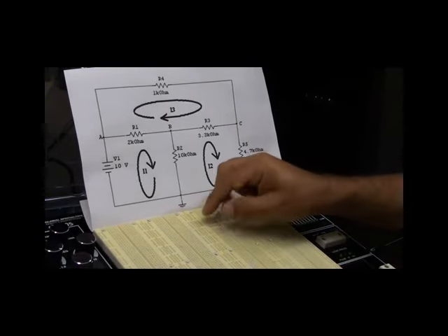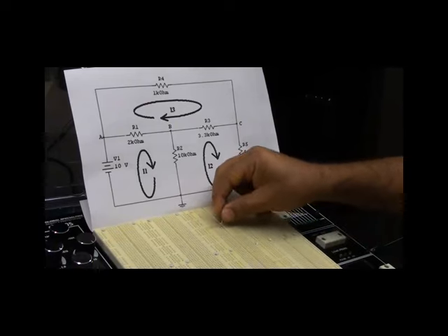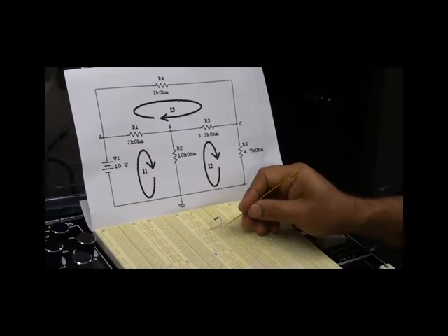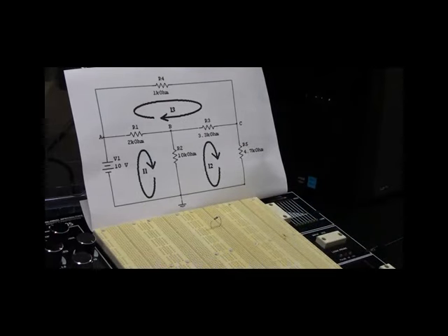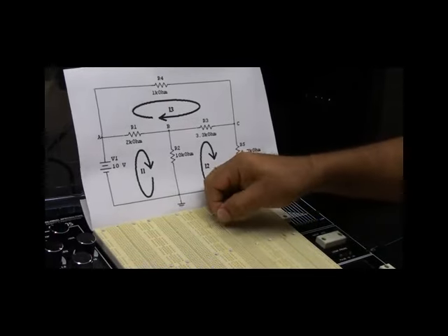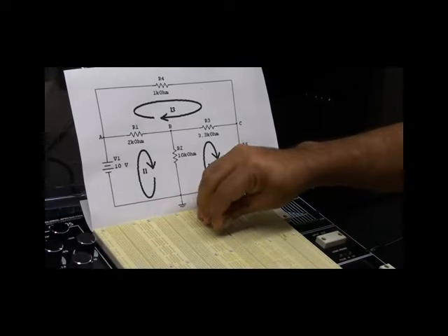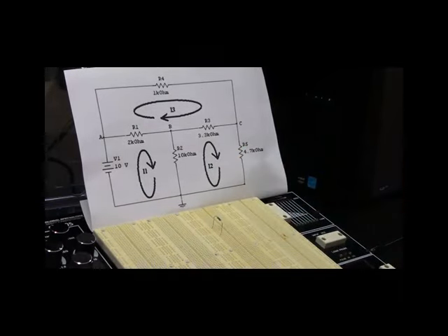Why? Because you have put both pins in a connected column. This means you are shorting the resistor. So make sure that you don't do that. Again, I'm going to put a horizontal resistor.